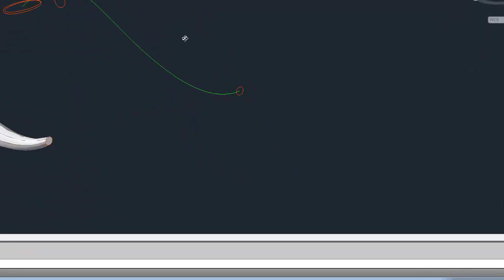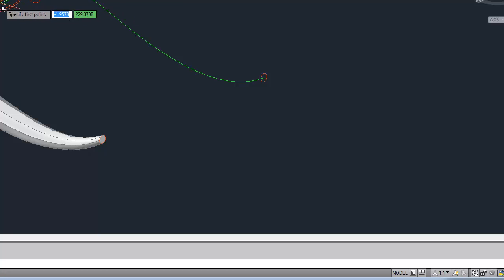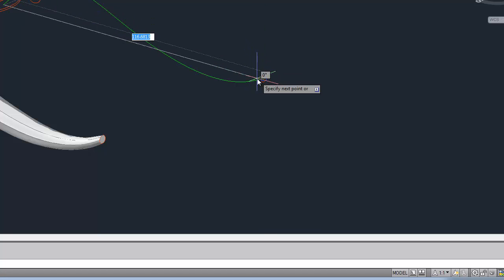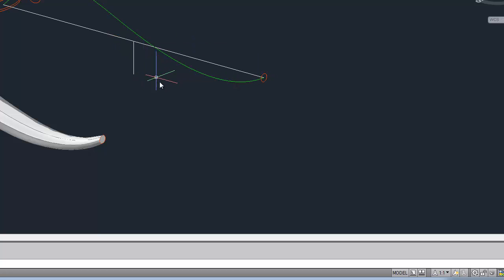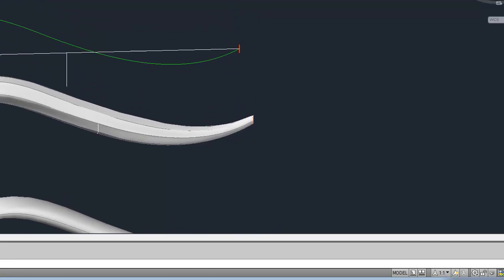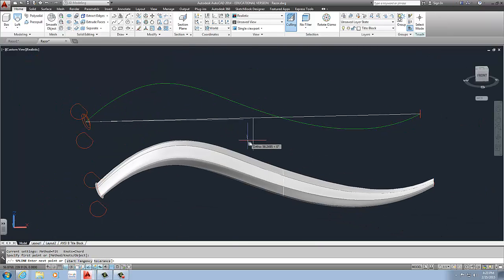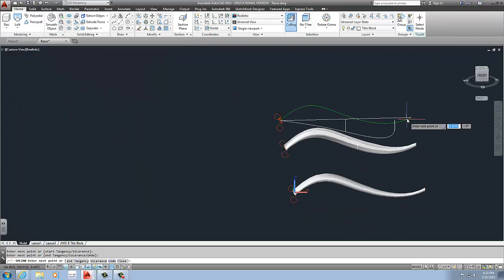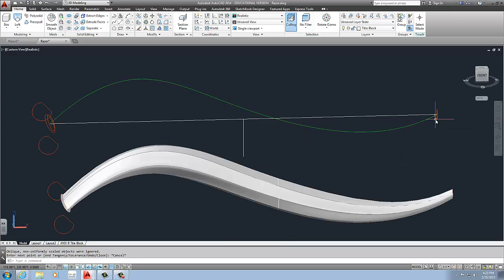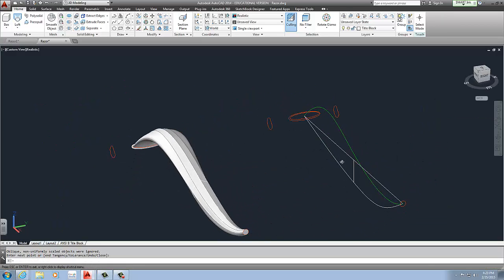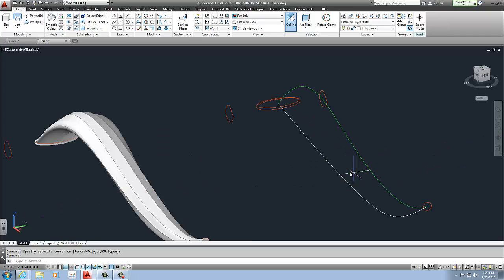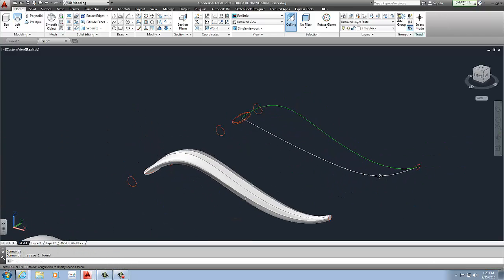You can additionally add different paths to this. So let's say I'm going to create, using these lines as references, a line right underneath, where I'm going to use a spline based on the same intersection point. Oops, I missed that. Clicked escape by accident. So that's my new shape. And another additional path that I'm going to be using for the circle.